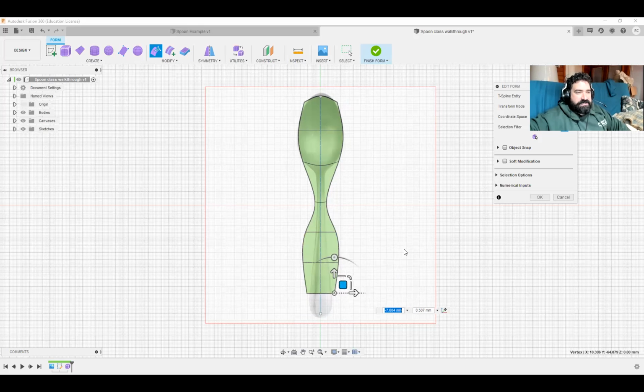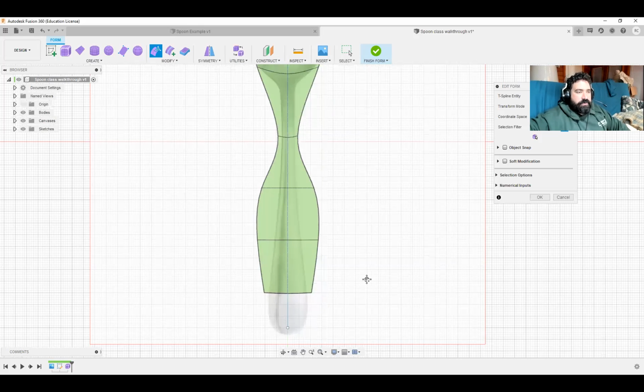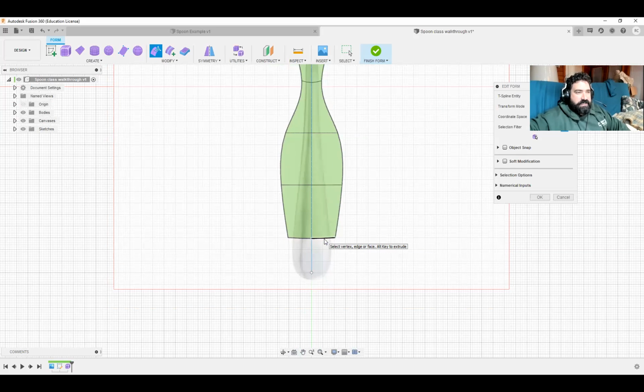Damn, I should have added more sections. No problem. You could extrude just like before. Select the line, press and hold Alt. Now drag, and it drags the whole thing. Now the problem is you didn't select that point, or I didn't.